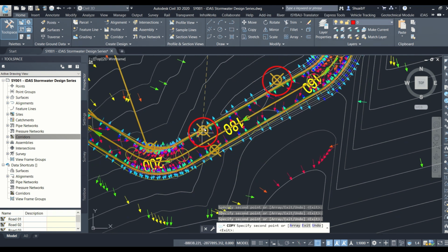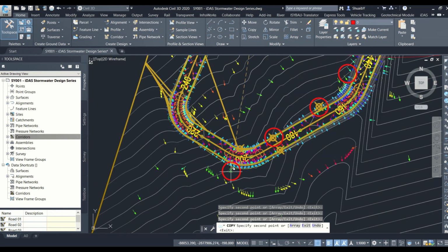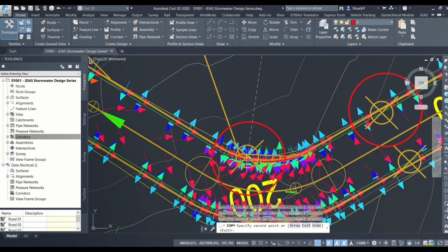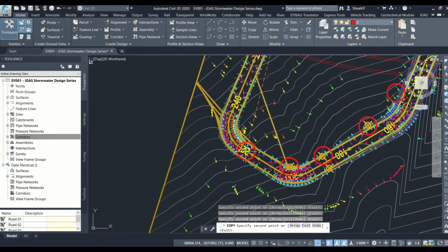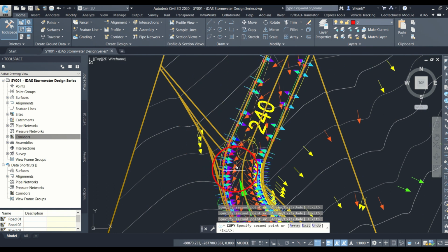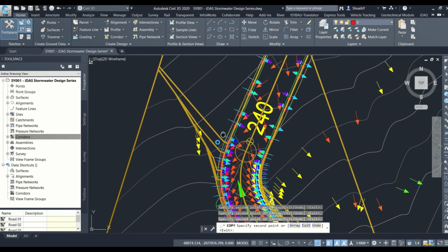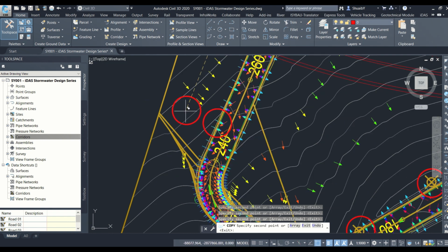Again, I've got two low points here. Again, I'm going to use that one because the water's falling away from the road at that section there. We're going to go here, maybe put another one here on the curve or just before the curve. Let's drop it here. It's fine. All right, we'll model that just now with the polyline. And then, of course, you can see what's happening there. It's more or less we need one before that curving, so that water's going to flow down there. We're going to drop it somewhere, maybe there, right?